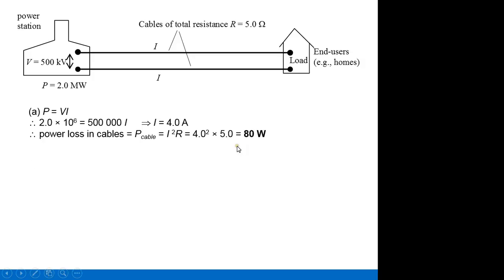At this point in time, I want to highlight this. For power losses, especially for this kind of AC question, can I recommend this? For power loss, always use I squared R. Can you write it down somewhere? For power loss, always use I squared R.